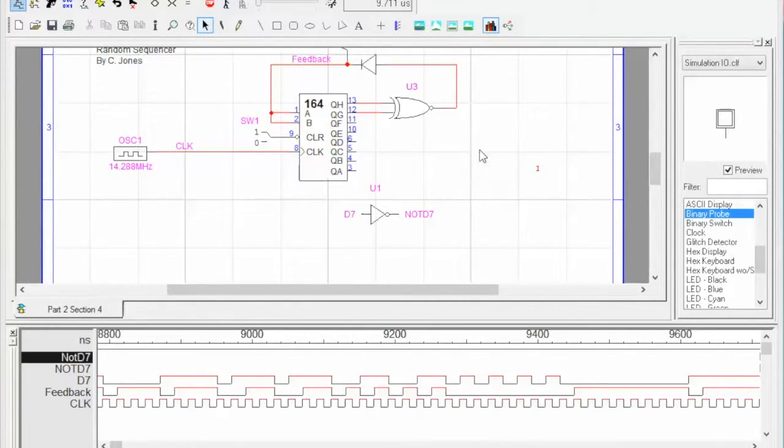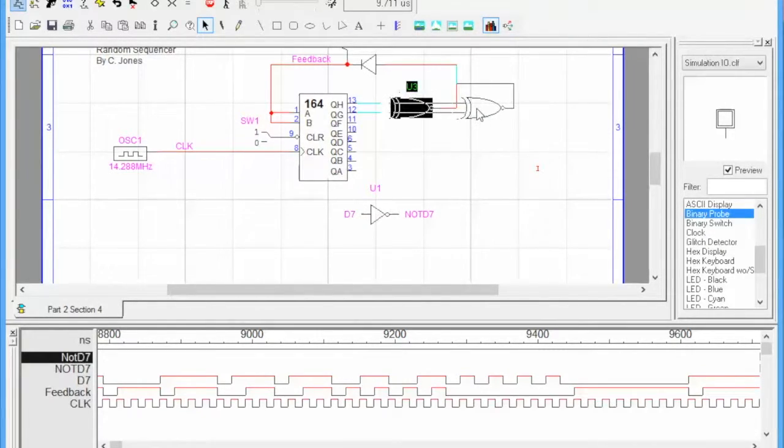Okay, now it's time to go on to busing, or how to create a bus using breakouts. So before we can do that, we have to make some changes to our schematic. So first off, let's pull this guy out a little bit, pull this fellow up, take the zap tool and get rid of this guy and this guy, maybe the label there and the label there, and we'll move this guy over a bit.